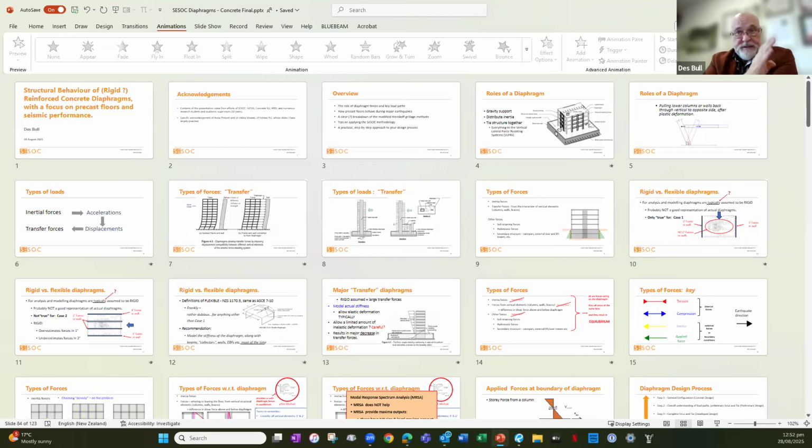You're far better, seriously, to apply earthquake loads north, south, east, west, and then on the 45 degrees. That would give you, in my mind, a better sense of where the loads are going inside the structure than 100 plus 30. 100 plus 30 is not a get-out-of-jail card, but you are required to do it at the moment. Right, that's good to know.